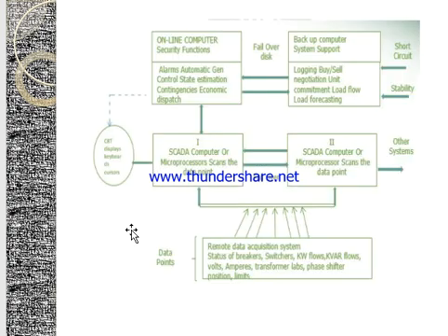While considering an electrical system, if there is a short circuit or a stability problem, then it will be sent to the SCADA system, and we have to sense it, and this will be sent to the control unit. That control unit will analyze whether the sent values, the current or voltage or power or frequency or angle, are within the limits or not. Prescribed limits have to be given, and whether it is exceeding the limit or below the limit, automatically control actions will be taken immediately by the SCADA. It can sense those values and immediate actions can be taken.